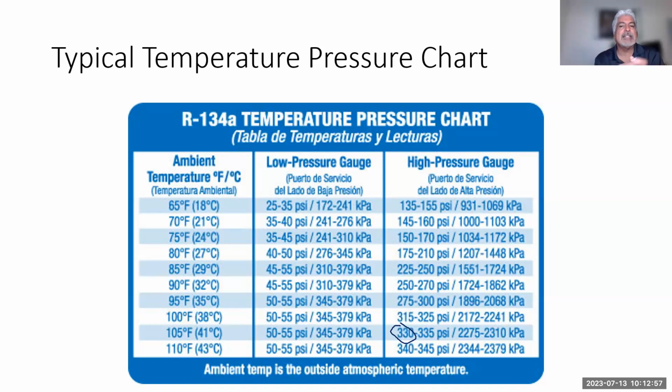It's so hot. So therefore, that compressor is going to kick on and fight however many pounds of pressure are already in there. So it's imperative that the clutch, bam, engages solidly, because it's going to be fighting some serious pressure initially. I call it the shock. It's shocking that compressor. So we need to make sure that clutch engages solidly.